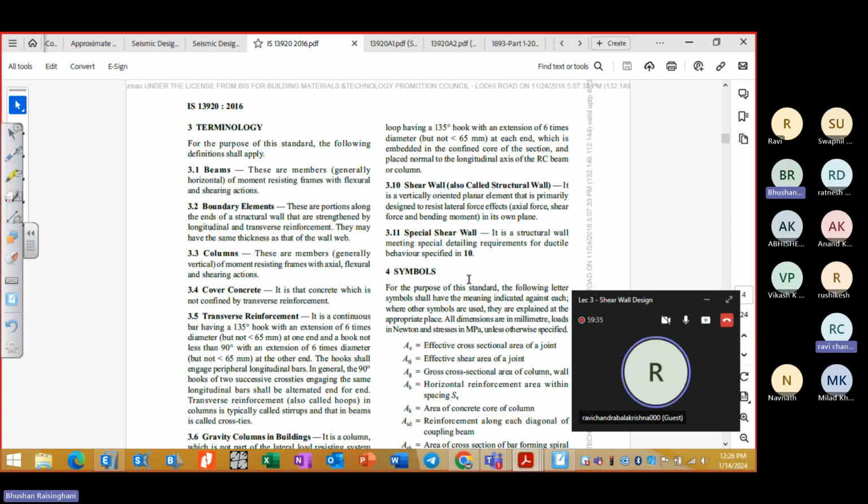So the membrane elements can support in plane, right? Membrane, like what we are designing as per IS 456-2000, the slabs. Okay, so they are designed as a membrane. So membrane element does not take any forces out of plane, it takes only in plane forces, and it does not participate in any resistance. So full force goes to the perimeter beams on which it is connected.